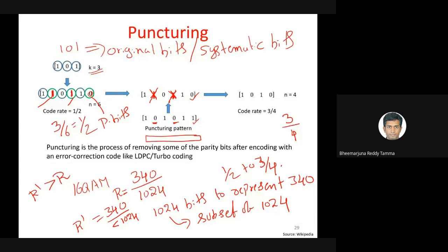So first, depending on the channel quality, that means using SNR, you are deciding what the modulation order and the coding rate should be. And since we have the soft combining feature, and you wanted to take the risk of some packets getting lost and retransmitted using the ARQ mechanism, you do the puncturing process, where you omit some of the parity bits. If it is unsuccessful, only then you retransmit these parity bits and use a process called soft combining to successfully decode to the extent possible.